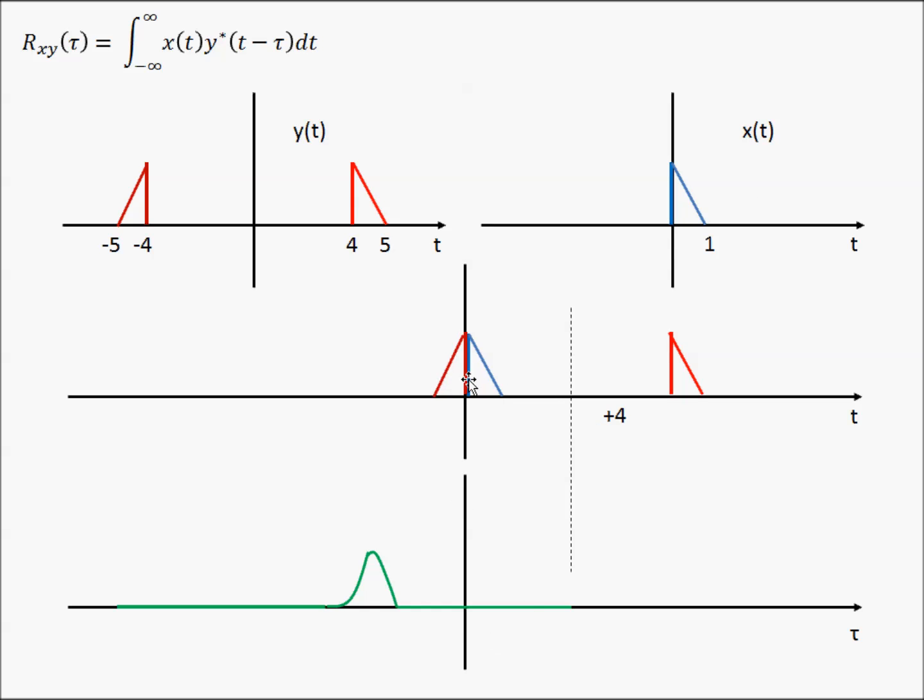So when this triangle reaches the x(t), again we get a non-zero value of the cross-correlation, and then when it shifts completely across, it's going to go back to 0 for the duration of the delay or the lag. So I haven't drawn these curves exactly, but they are representative of what you're going to get. First thing to note is that the peak of this portion of the cross-correlation function is going to be larger than the peak of this portion of the cross-correlation.